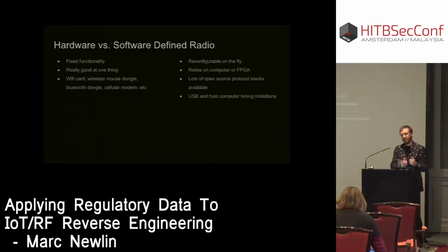But if you don't know what that thing is that you need to do, it's not going to be very useful. So software-defined radio allows you to have a high degree of reconfigurability. So you might have a wide range of frequencies you can tune to, varying bandwidths. But the drawback is that it doesn't know how to do any one thing. So the SDR will just send this raw radio data to your computer or to an FPGA. And then you have to implement the functionality that makes it a Wi-Fi radio or a Bluetooth radio or whatever. But it's a very useful tool for doing this kind of reverse engineering because you can reconfigure it on the fly as you're figuring out what it is that you're looking at.